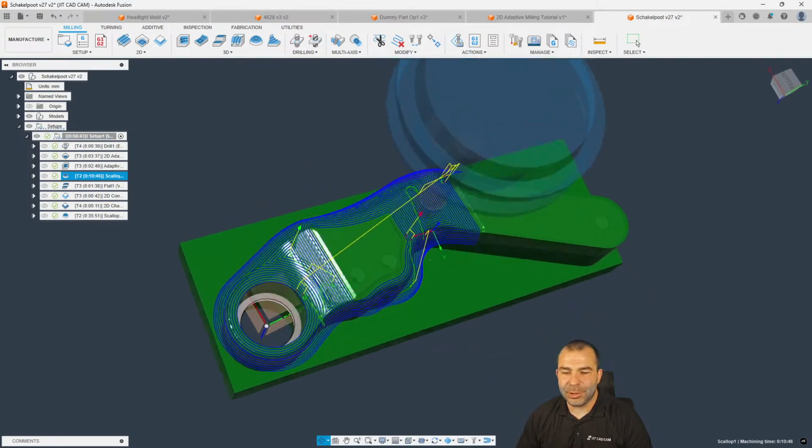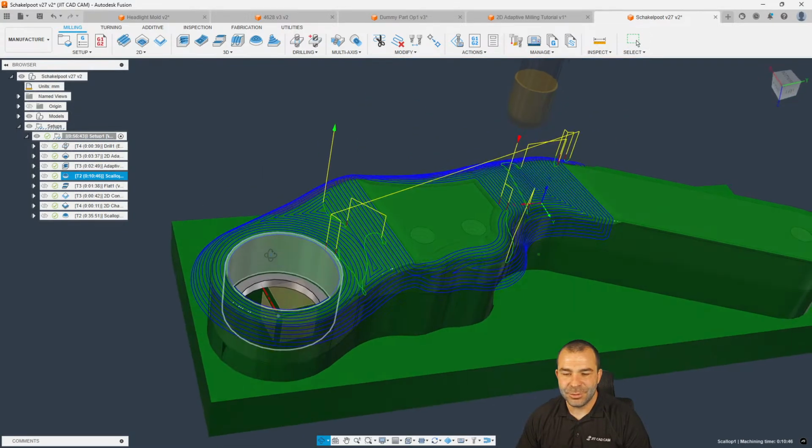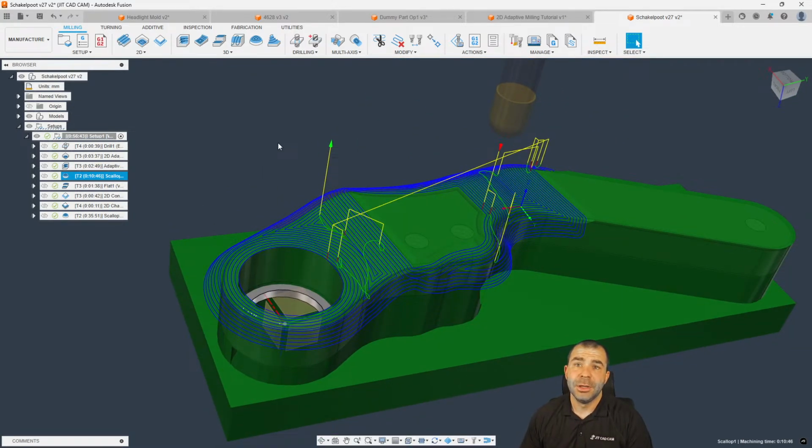So this is actually a pretty good part that we have inside of Fusion 360. I always ask people, when you're dealing with wanting to do what I would call an in-process inspection, or a probe geometry as Fusion has it, how critical is that tolerance? Do we want to pre-cut something and then measure, then post-cut it? Or are we running 1,000 parts where we can measure every one and then just cut it after and be okay? And we're going to set up both scenarios here.